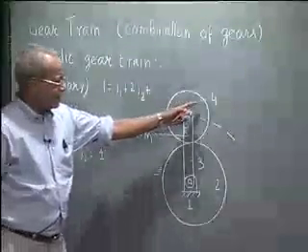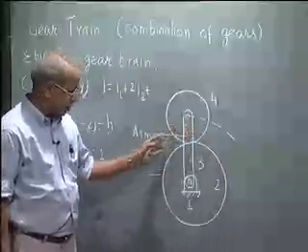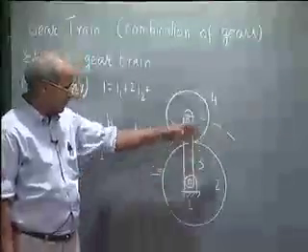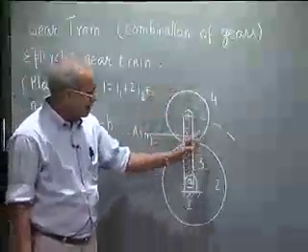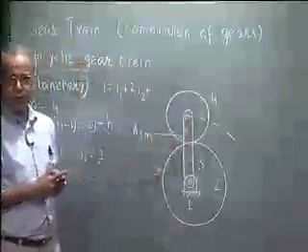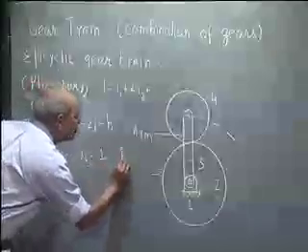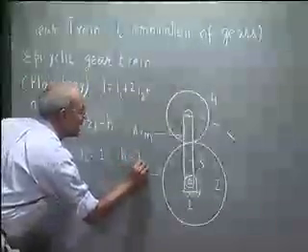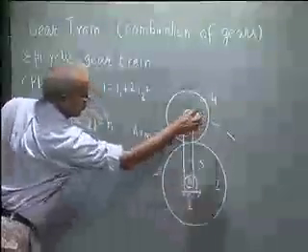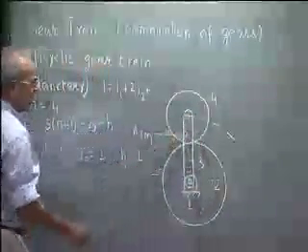And between gears 3 and 4, these are the pitch circles. Let me not draw, these are imaginary circles representing the gears. Between 3 and 4, we have a gear tooth connection, which is a higher pair. So h is 1 there, and between gear 2 and gear 4, they also have a higher pair.